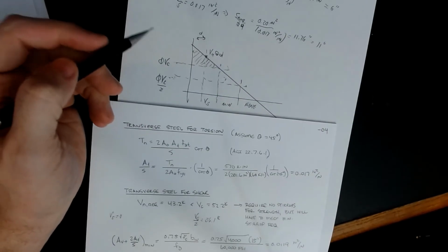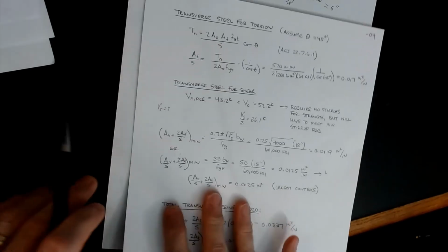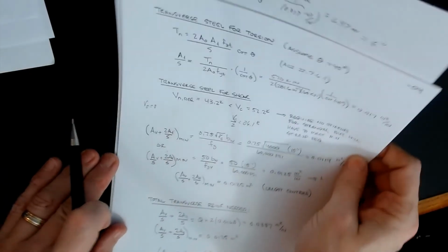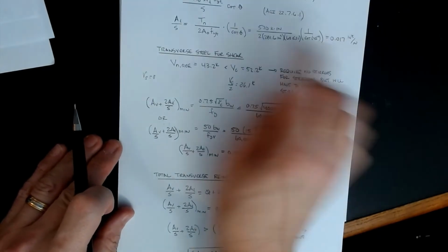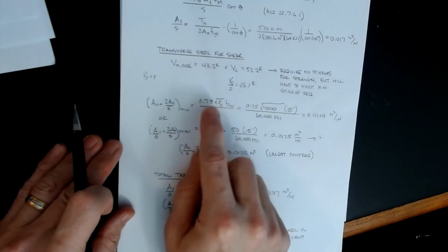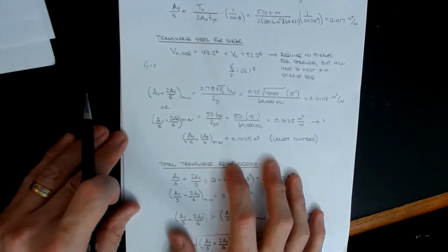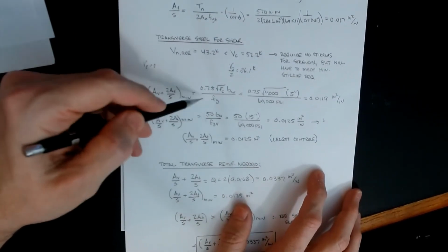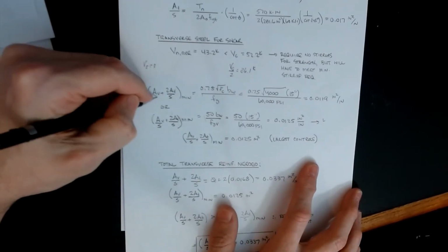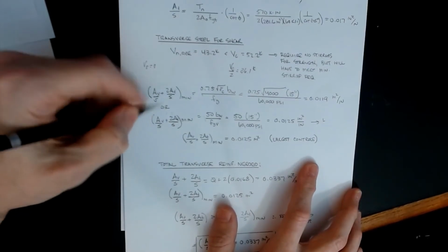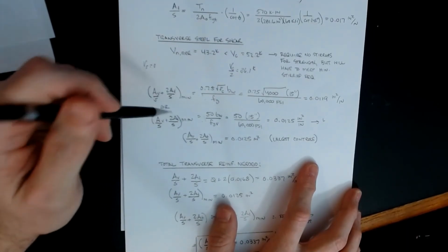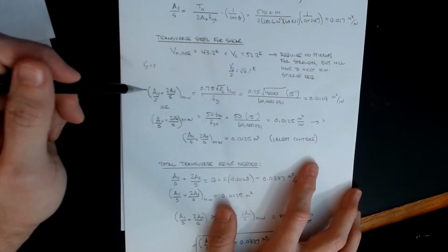Okay? Because I need that minimum in there, we've got to figure out, well, I don't need any technically for strength because our Vs is going to be 0. But I do need a minimum amount. So this is where we look at our minimums. And if you'll remember, you'll recognize these two formulas when we did Av over s minimum. It was this. Well, now when I throw torsion into it, I can count the torsional steel as part of the minimum for the shear.